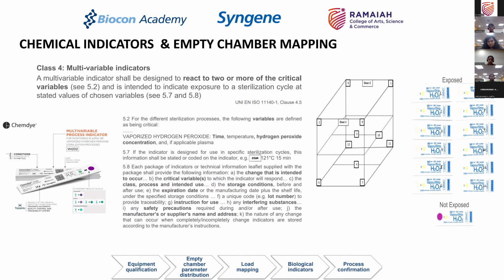So you place these chemical indicators throughout the chamber, run the dose, and see if there is sufficient exposure of H2O2 within the chamber, because you are doing an empty chamber mapping, making sure that your empty chamber is exposed properly to the VHP dosages or the VHP concentration to achieve the right sterilization cycle.